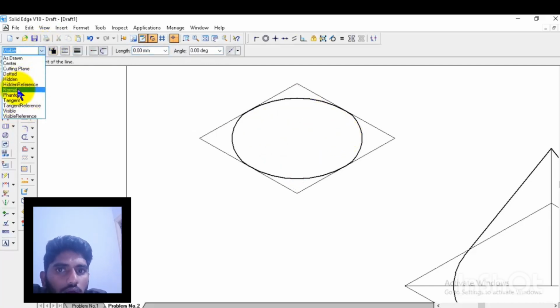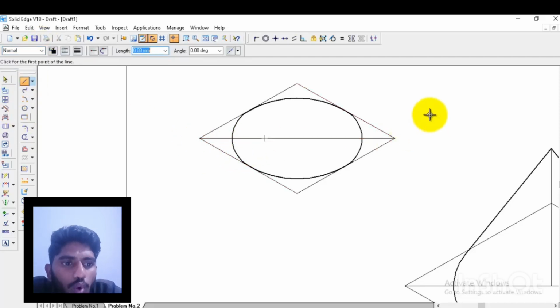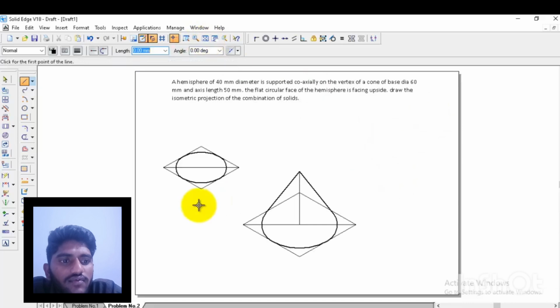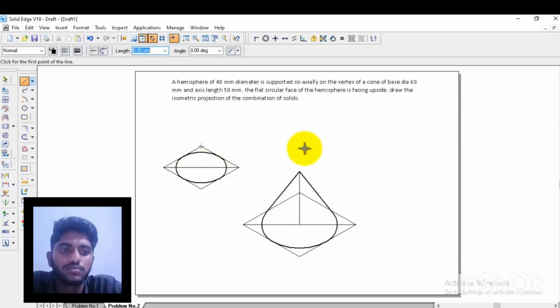And now go to the arc by center point and visible line, take the bottom corner as center and draw the arc between the two midpoints, and in the same way take the top corner and draw the arc between the bottom midpoints and the right side segment. Take the right one, and once you finish you can zoom into the remaining hemisphere. This is the circular portion of the bottom. We will get the curve.